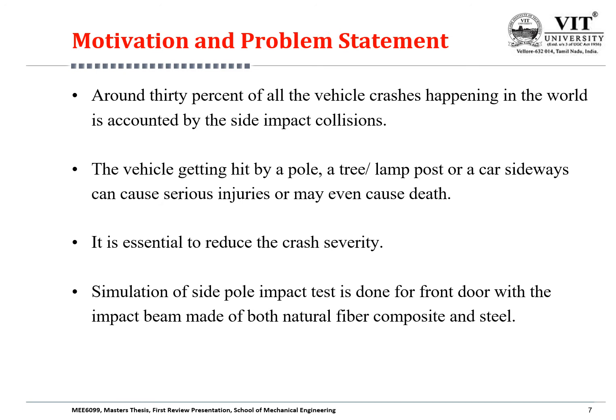Out of all the crashes that's happening around the world, 30% of all the vehicle crashes is accounted by side impact collisions. This could be explained with an example such as vehicle getting hit by a pole, a lamppost, a tree, or even a car sideways, which can cause serious injuries or even may cause death. So it is very essential to reduce the crash severity and increase the crashworthiness properties. In this project, simulation of side pole impact test is done for front door with the impact beam made of both natural fiber composite as well as steel.